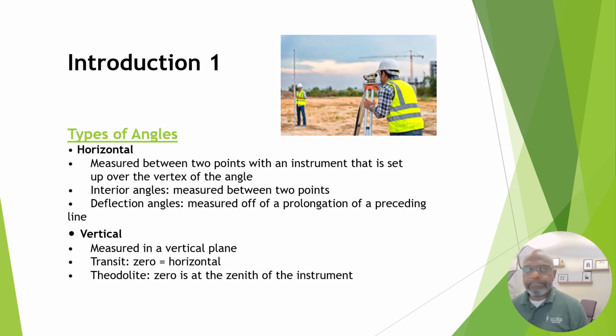So again, when we're looking at horizontal angles, that first point is looking at a circle and setting it to 0. The scope we are using is then turned to the second point, and the angle measured is read from the angle measurement circle on that device, on that transit. So it has a full scale around it.